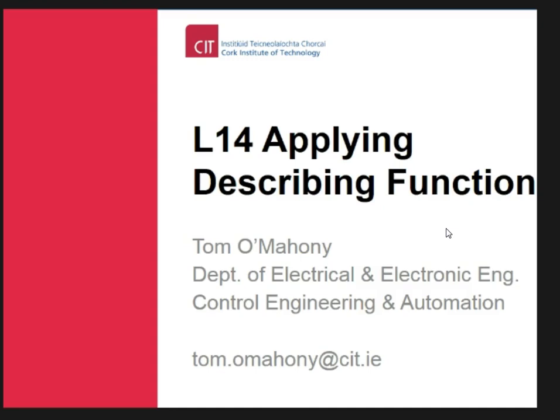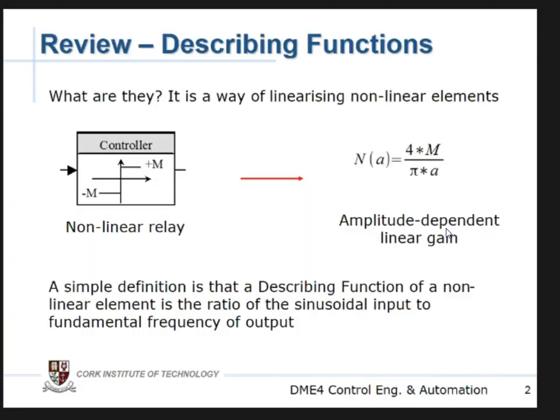Okay, so to finish off the section on describing functions, to start off by recapping where we finished off last week, we were looking at the concept of a describing function. The purpose of them is to linearize nonlinear elements, or it's one way. There are different ways in which we can go about linearizing nonlinear elements, but the idea is that the theories that we have, such as Laplace, only apply to linear systems.